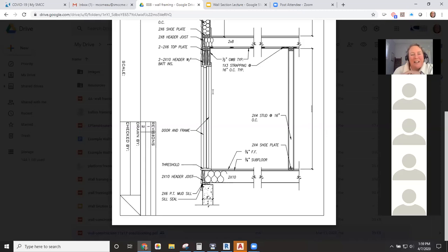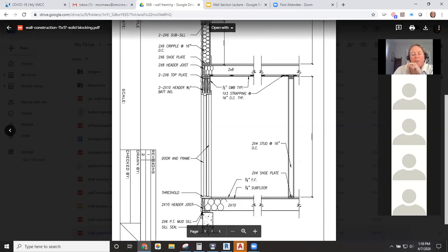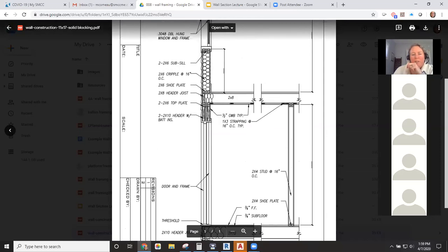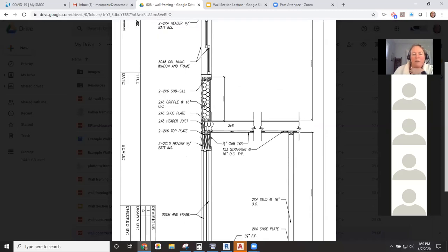But in reality, when I'm picking out a header size here, I need to take into consideration the weight of the entire structure. This header, for instance, is holding up this whole second floor, plus it's holding up a roof. When you consider the load applied on the roof, that's a 50-pound snow load, and then we have a full second floor, and the header's holding all that up.